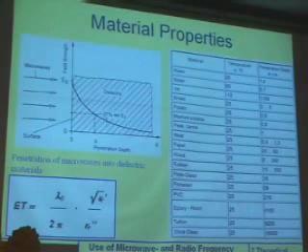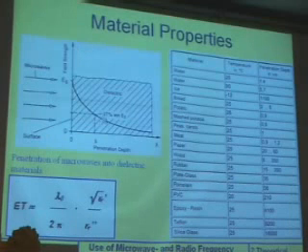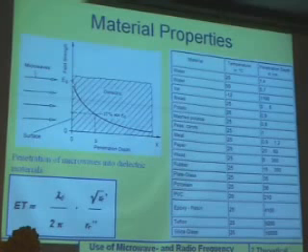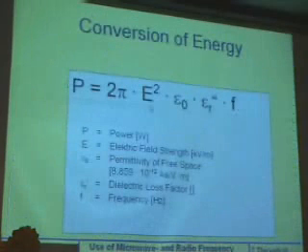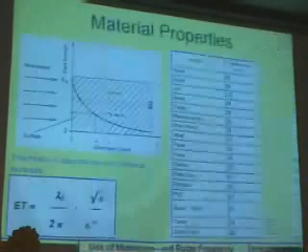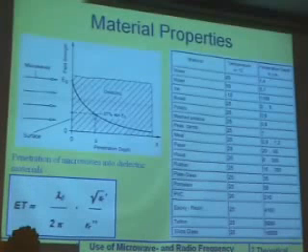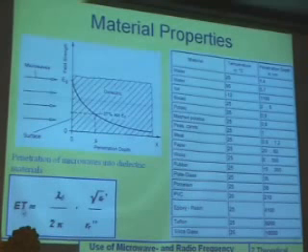And if you divide 1 through the Euler number, you get the exact result of 0.37 or 37% of the value here at the surface of the material. This is E0. This is the electric field strength on top of the material, and the active penetration depth is restricted down to 37% of E0 here at the surface. This is the active penetration depth, and the effective penetration depth here is shown in a mathematical calculation.